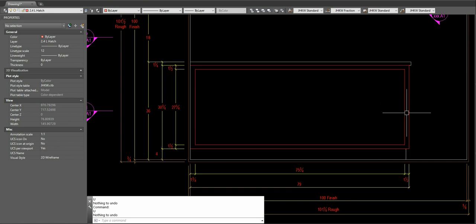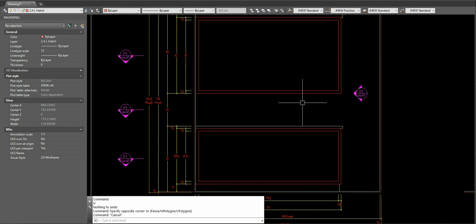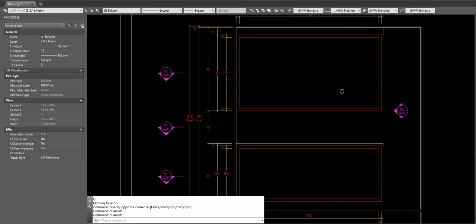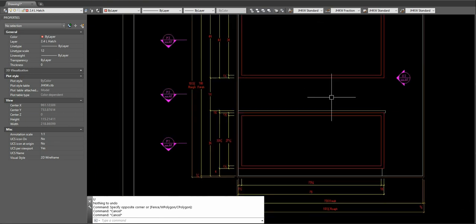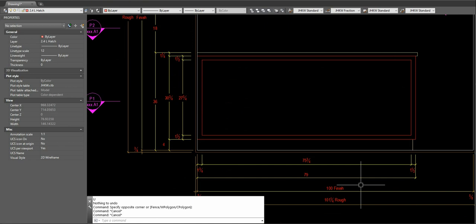that the plan acts as a legal document, and if someone looks at this and says, I approve this, and we build and install this, everyone knew what they were getting. If I just send you a 3D view of an elevation and you say, wow, that looks great, and I deliver it, and let's say there's a door casing here that I was too close to, or there was some plumbing or electrical that, even though a GC on site had my set of plans, if there's no dimensions, they don't know. They just can't know.